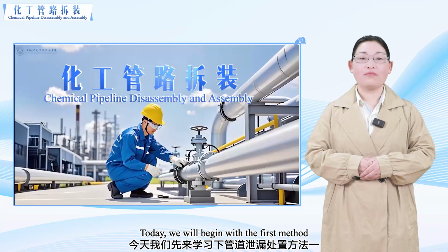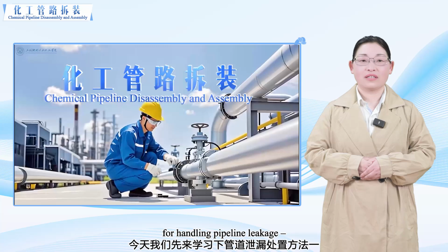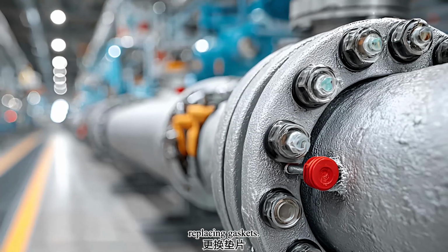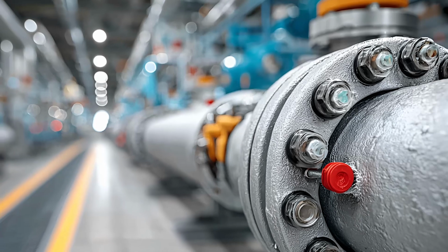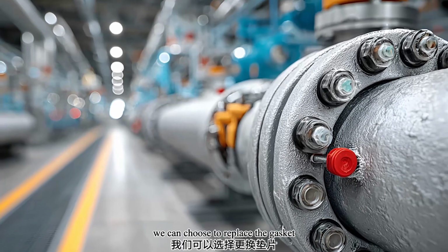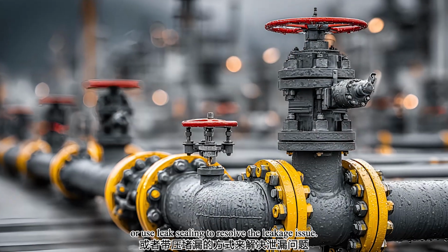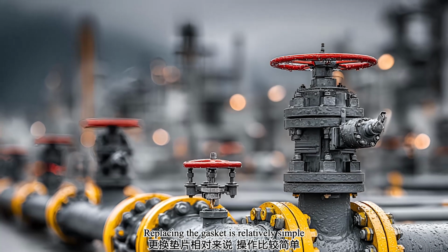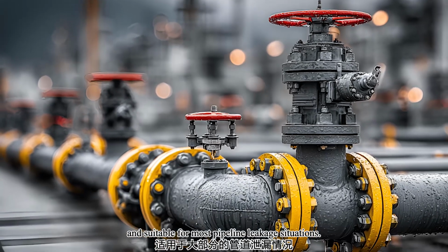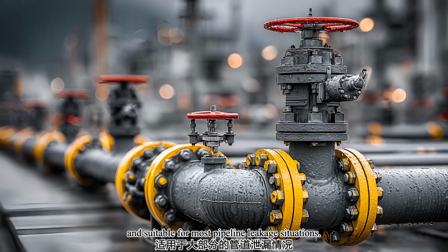Today, we will begin with the first method for handling pipeline leakage, replacing gaskets when a flange on a pipeline leaks. We can choose to replace the gasket or use leak sealing to resolve the leakage issue. Replacing the gasket is relatively simple and suitable for most pipeline leakage situations.